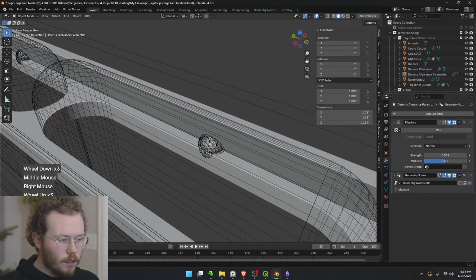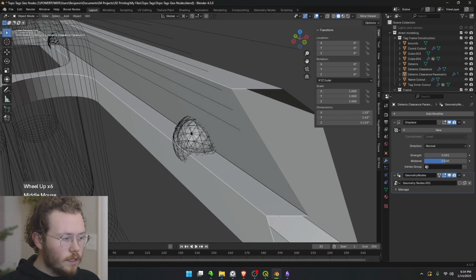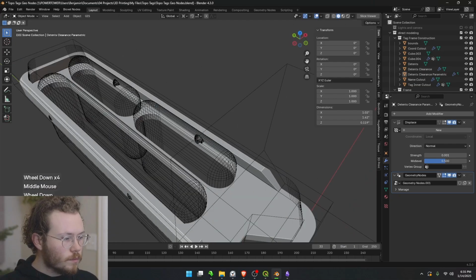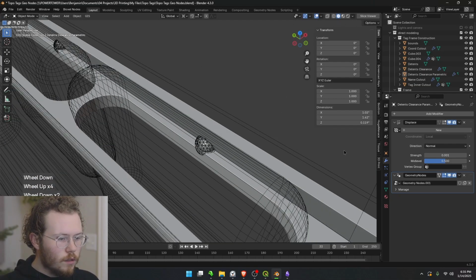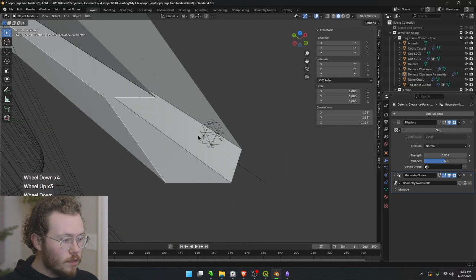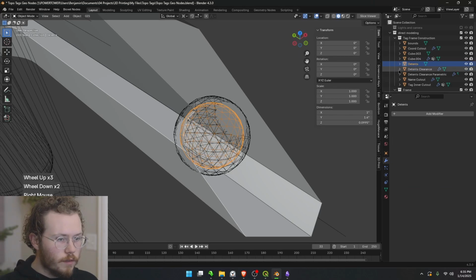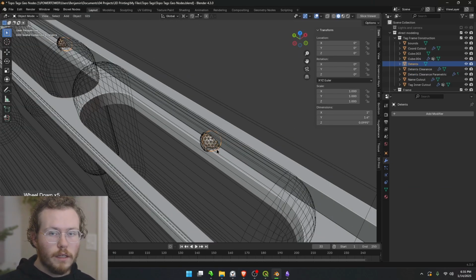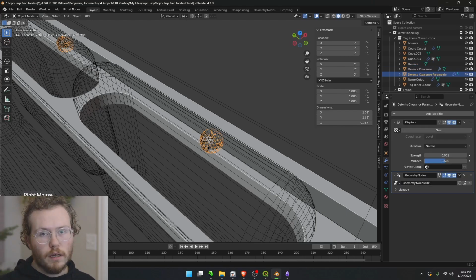and I'm just using that here to make sure that the detents have enough clearance to snap fit in, but not to try and press fit and bulge the sides of the frame out. So nice little thing, and because they're based on the same core geometry of the detents, if I modify this, the detent clearance will update, and that is the object that I would be cutting out of the mating features.